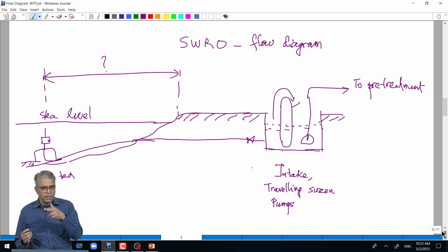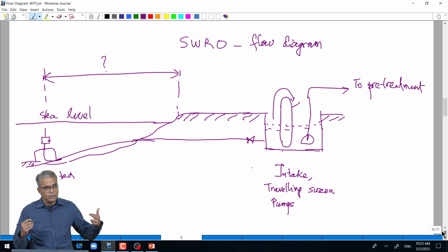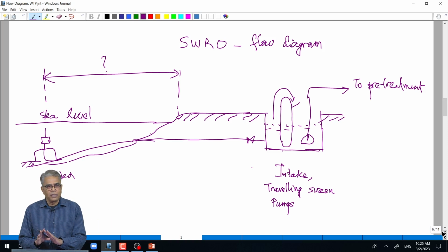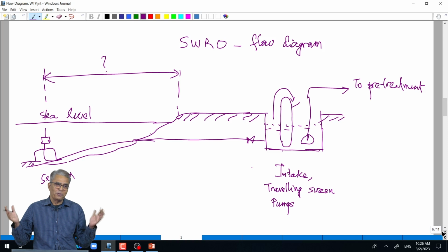Now, you will know most of the equipment is written down. Where the pumps are written, you will have to know the flow rates of the pump, you will also be able to estimate the discharge head required. Good old Fanning's friction factor: you have to know the size of the pipeline, the length of the pipeline, how many bends and valves you go through. You get it, calculate the hydraulic horsepower requirement, then the efficiency of the motor and pump combination, and you will get a hang of the actual power consumed. This is only for pumps; you have to do that for all electricity consuming equipment, including the light that you provide for that place, etc. It will be a small amount, but you can't forget it.